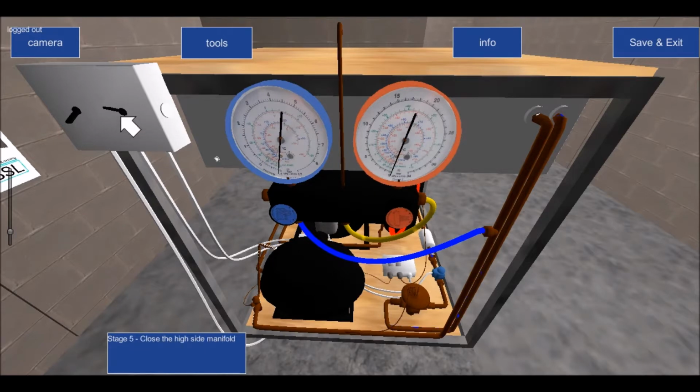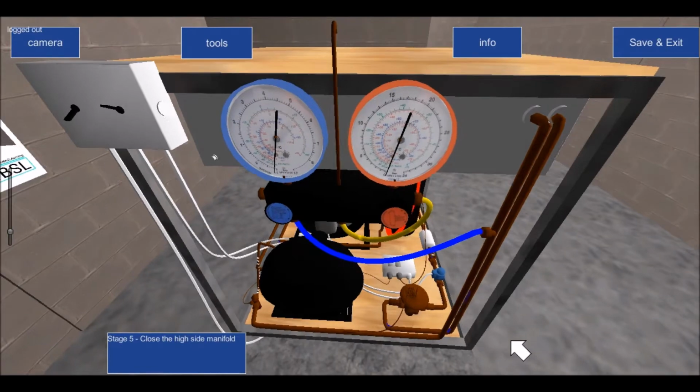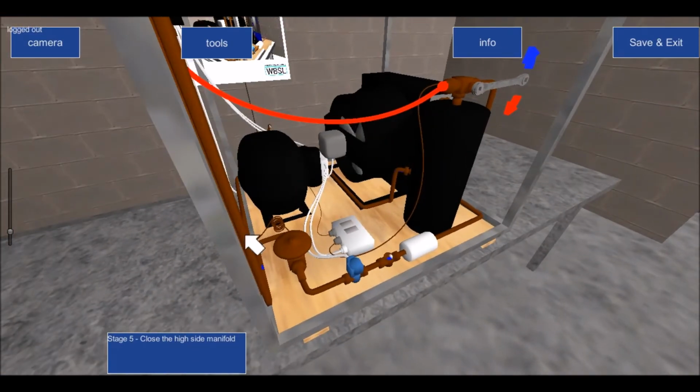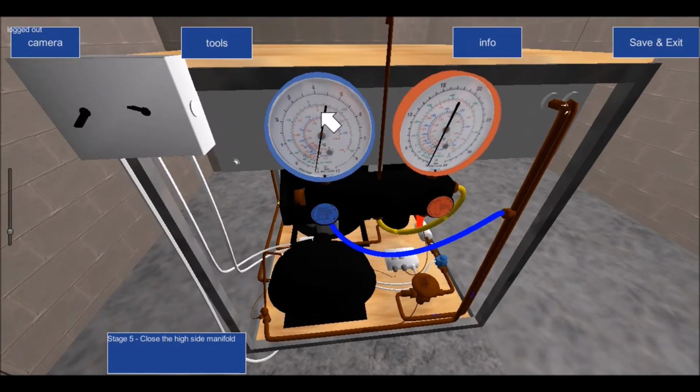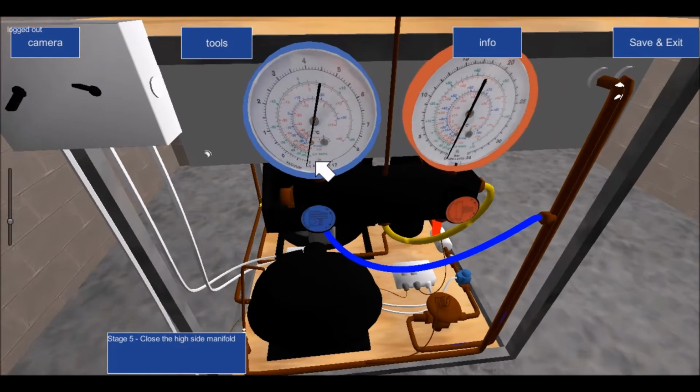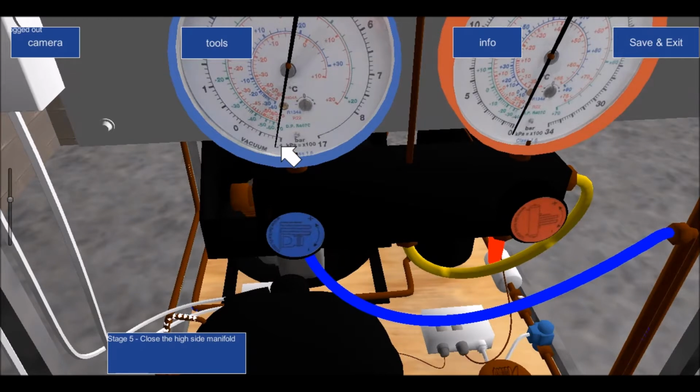If we look at our own system, this coil here is de-energized. So my room stat has killed the power to the solenoid valve. No liquid refrigerant can go past this solenoid valve. And what you saw happening then on my gauges is I went from 4 bar down to 0, right? 0 is here. There's a little programming problem. It shouldn't be registering -1.